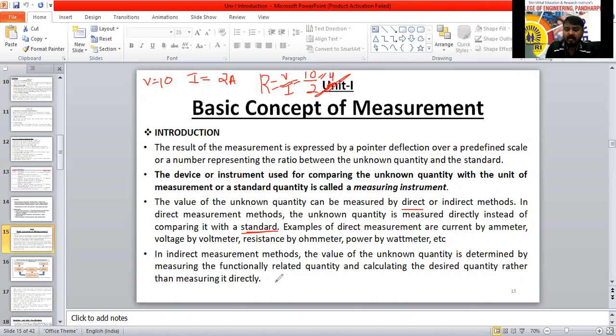By connecting an ohm meter, we can measure that resistance value. For the same circuit, we have to connect an ohm meter and cross verify, or compare with the standard value here. Then we can tell whether it is correct or wrong.